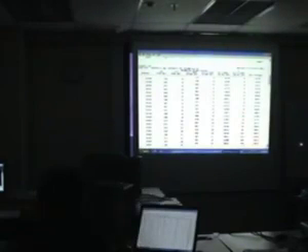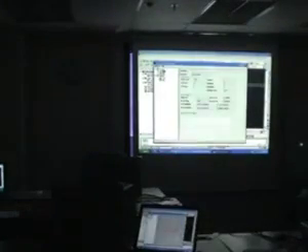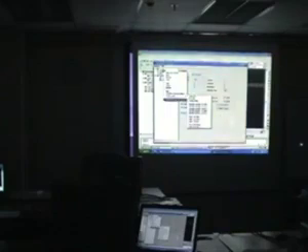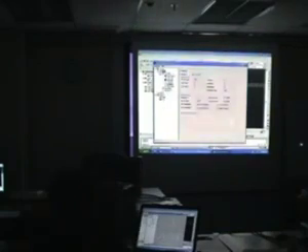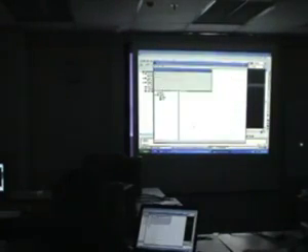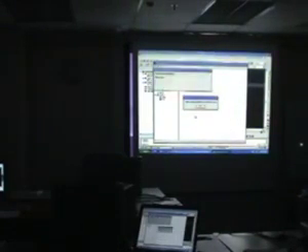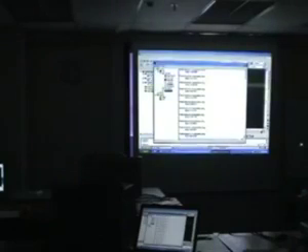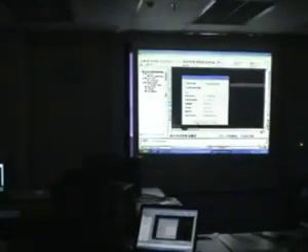Then you sign at the bottom. Now I'll show you the watershed boundaries. This is under the Terrain Model Explorer. You open up OGL, go to watershed, and you right click on watershed and calculate watershed. This basically calculates the catchment areas of the surface. So you can see all these watershed IDs. If you want to put them into the drawing, you just click import watershed boundaries. These are the layer names.